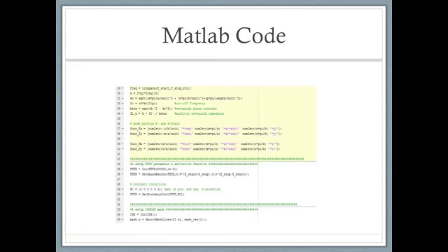The next part of the MATLAB code: the first line just creates a frequency vector of 201 linearly spaced numbers from the starting frequency to the stopping frequency. The next few lines initialize the cutoff frequency, the waveguide phase constant, and the analytical waveguide impedance. Also, the magnetic field and the electric field are introduced and implemented with the functions from my research for the specific mode I'm implementing. The second half of the code sets up the FDTD parameters, excitation function, and boundary conditions.